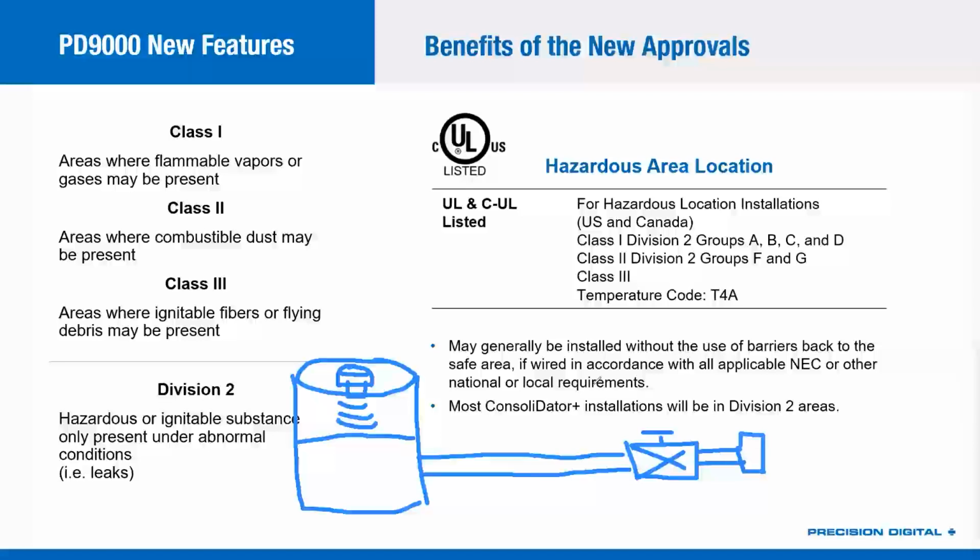Well, I can say that the insides of that tank are clearly Div 1. However, on the outsides of that tank, I might have exposure to that hazardous material. What if this valve leaks? Or what if there's a spill at the truck? Or what happens if some junction with the tank is a failure? Or somebody leaves a vent open? Or there's another kind of spill from the top of the tank? There could be a scenario you could imagine where I would have those hazardous materials nearby.